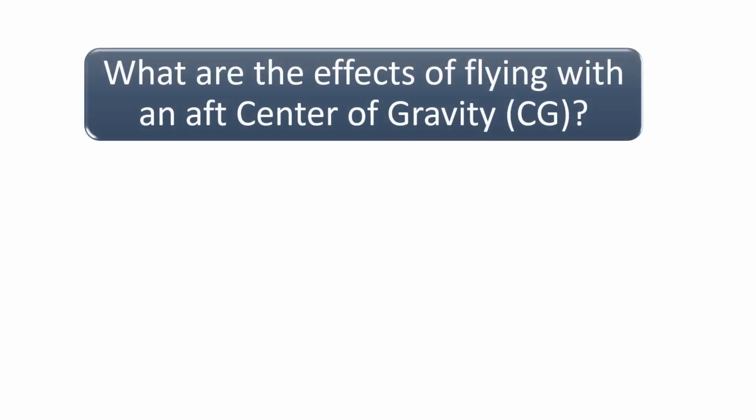What are the effects of flying with an aft center of gravity? An aircraft with a center of gravity that is too far aft of limits is susceptible to becoming very difficult to control, making spin and stall recovery very difficult or impossible.